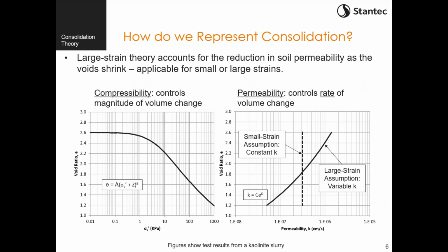All right, so how do we represent consolidation? Ultimately, consolidation can be broken down into a load-dependent component and a time-dependent component. All right, so these are two key points. Classical consolidation theory, we assume a constant permeability. So this plot on the bottom right, we see what classical consolidation theory would assume.